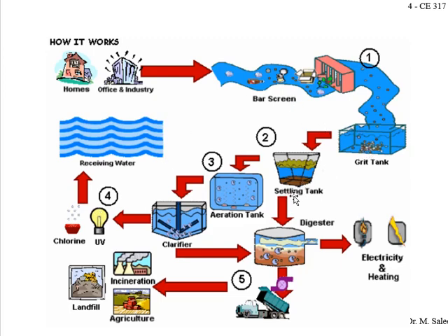And from the bottom of these tanks, you see some solids are settled here. Here also some solids are settled. These solids can be put in a tank which is called a digester. So the solids from here and from here will go to a closed tank where we heat the tank a little bit. It will create an anaerobic environment, that is, there is no oxygen. So another type of bacteria will grow and they will reduce the waste material.